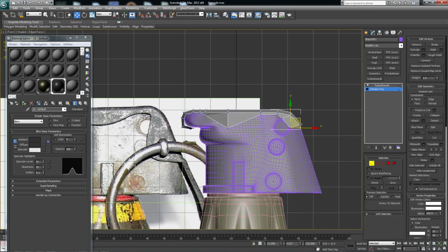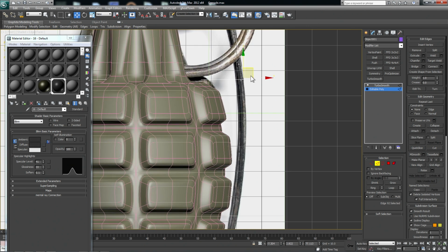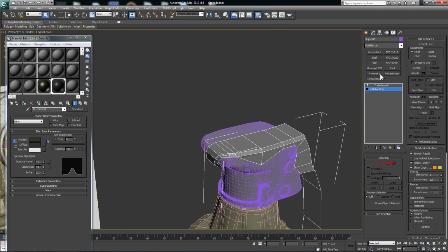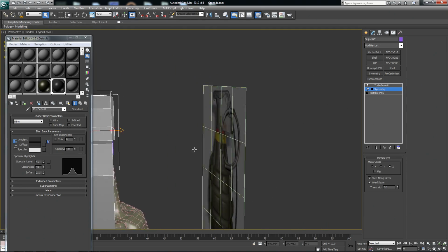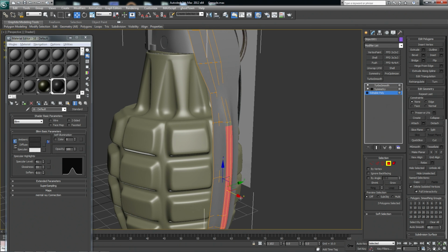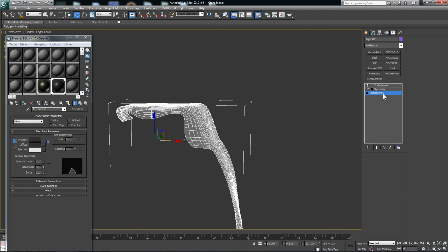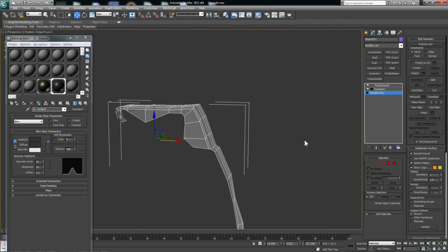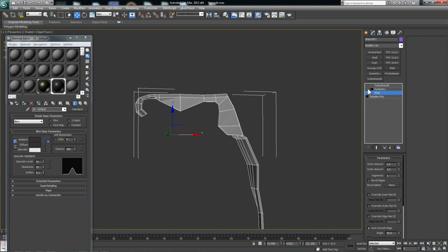Alright, so I modeled this back piece out using the same edge modeling technique, so hopefully you realize how versatile this workflow is. I've also set up a symmetry with this piece as well, and now we can start looking at the whole form. After looking at some additional reference, I've decided to add some grooves on this back safety lever. Okay, now to add thickness, let's jump to our edit poly and then add a shell modifier so that it inserts before our symmetry and turbo smooth.